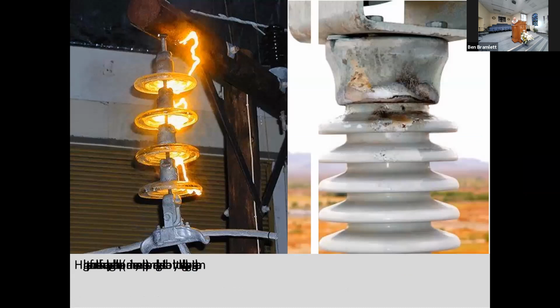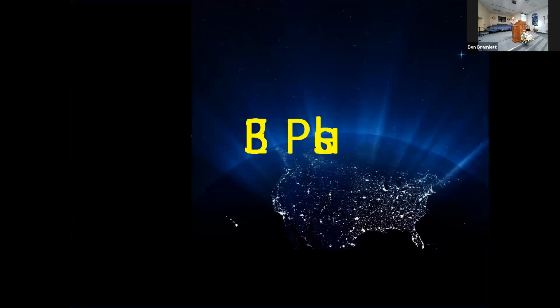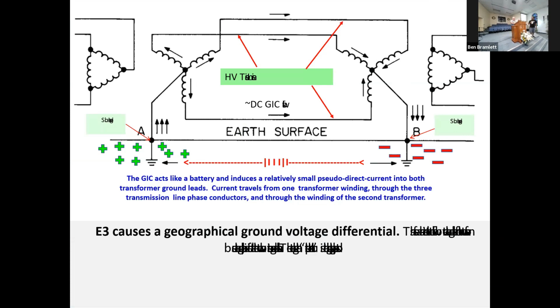Here's another picture on the left side of a flashing over insulator string. Okay, if you have a transformer that's got these big bushings and bells on it, there's a possibility that you'll destroy the bushings and not kill the transformer and its iron core on the inside. That's not guaranteed, but it's always possible. All right, we're talking about the E3 pulse here.